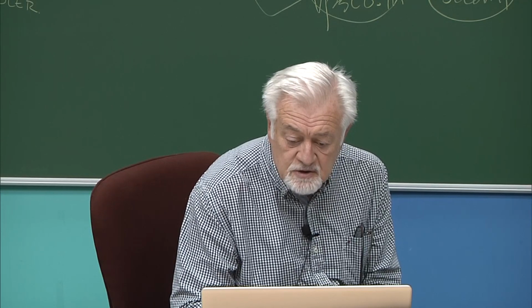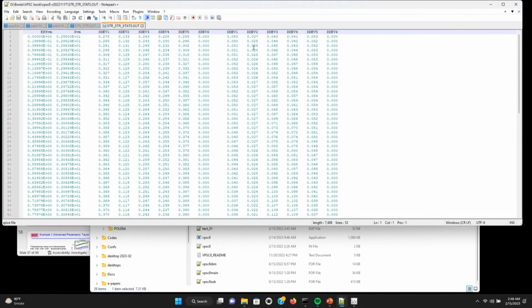And here, as you can see, the deviations in all the components of the strain rate from 1 to 5 are much smaller than the deviations of all the components of stress. So that already gives you an idea of how you are accommodating the deformation and what the systems are doing. These are useful information to see how the assumption that you use for the interaction is working as far as distributing the strain among the grains.